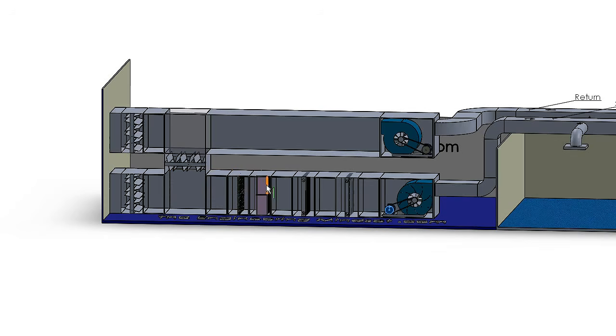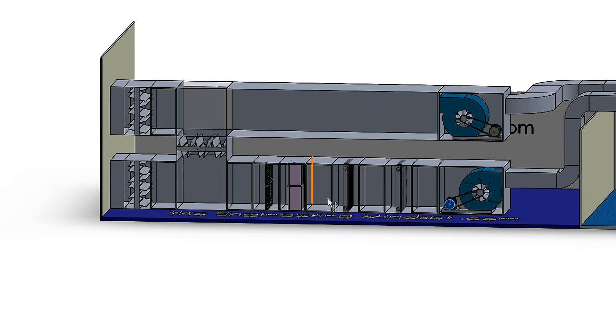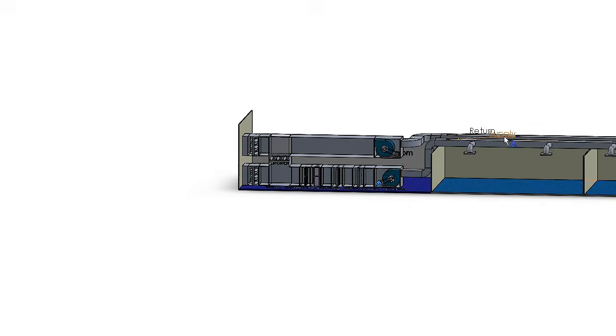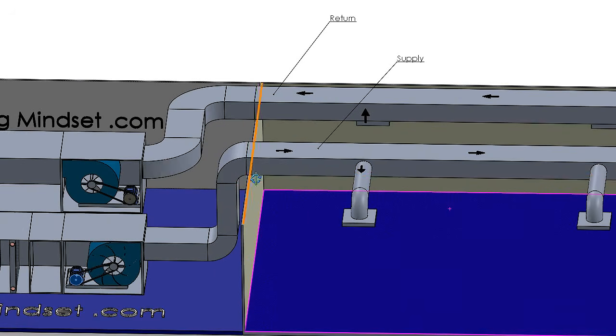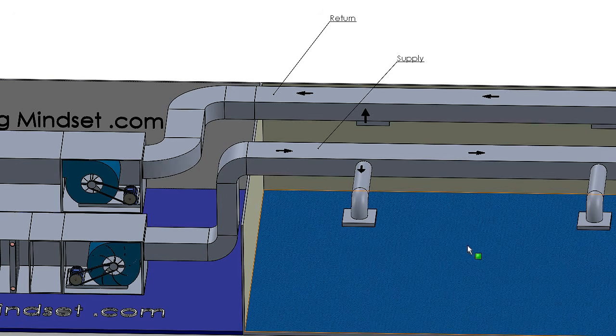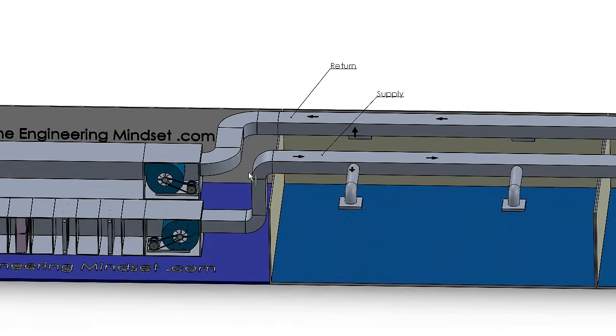Here we've got two layers of filtration protection. Then we're going to heat or cool the air, maybe to change the psychrometric properties of the air. And what's been pulling all that air this whole time is this fan there, which then drives this and sends it off into the space, into the offices, where the air is dumped. It conditions the space inside the building, keeps all the occupants happy, and then returns back here through this way.